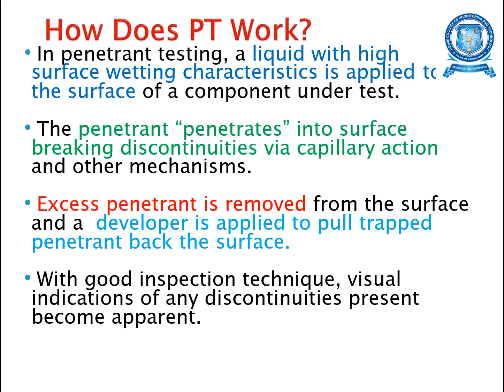So how does this penetrant testing work? In penetrant testing, a liquid with high surface wetting characteristics is applied on the surface of the component which you're going to test. So this liquid is nothing but the penetrant. The penetrant penetrates into the surface discontinuities due to the capillary action and other mechanisms.